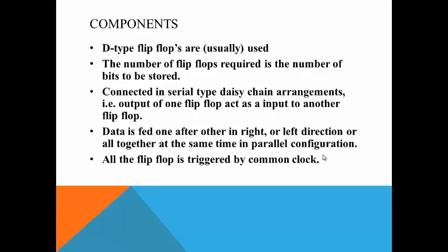The basic components in a shift register are D flip-flops. D flip-flops are data flip-flops or storage flip-flops, so it is the simplest flip-flop. It can be used for data storage. So usually we will use D flip-flops, and the number of flip-flops required will be the number of bits you want to store, and then they will be connected in a serial manner, in a series daisy chain arrangement.